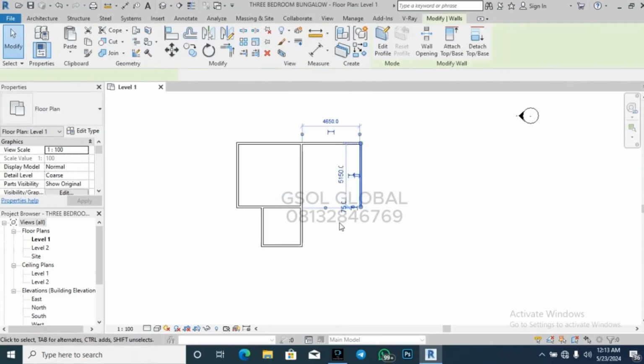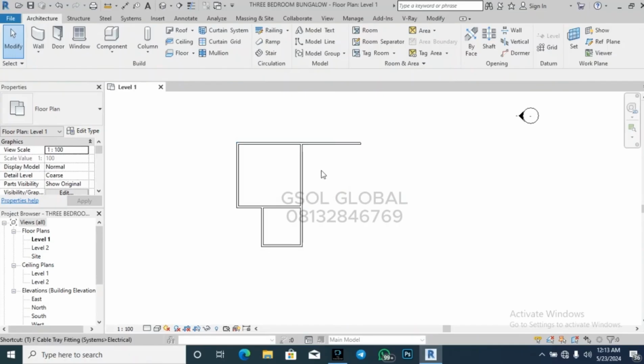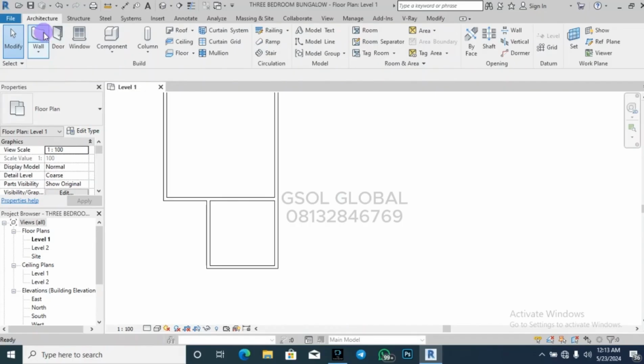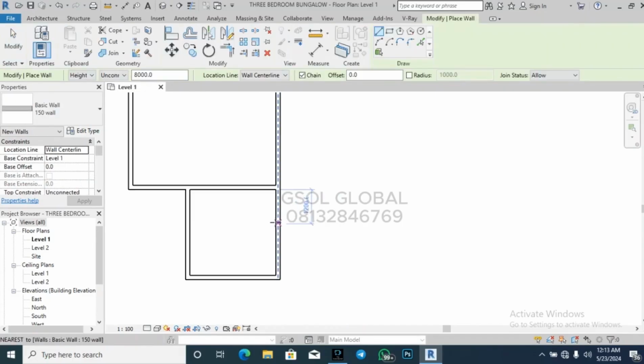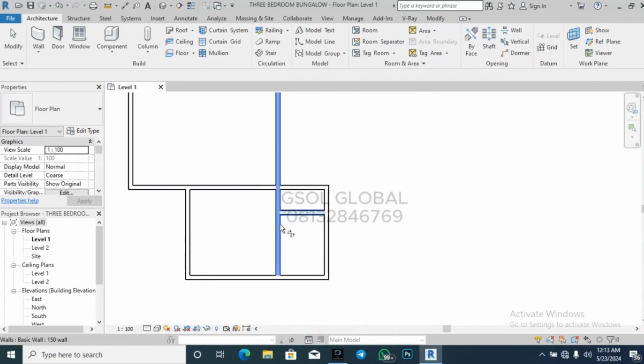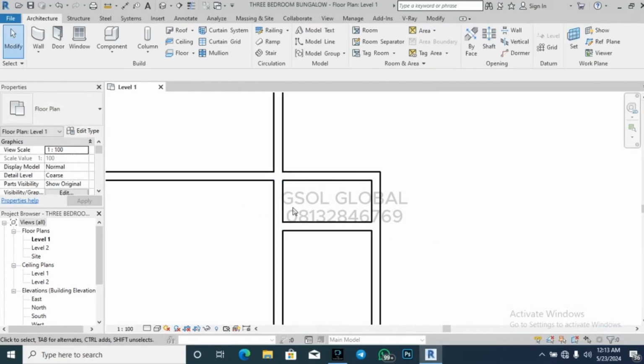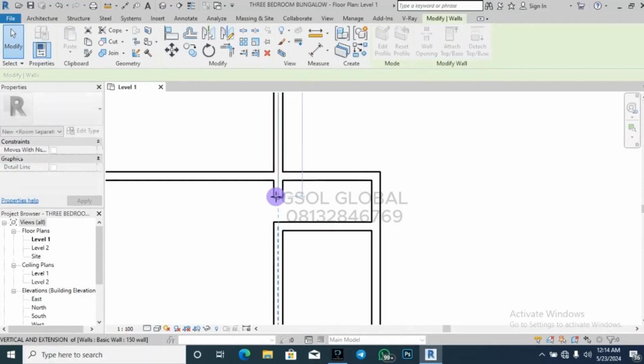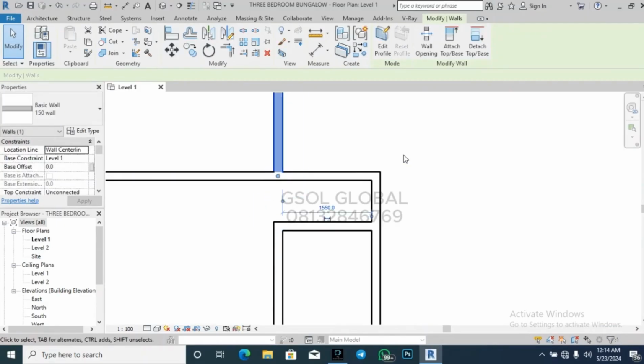Okay, so let's go. I've already seen what I want to see. All right, so now trim and let's trim. I will just go ahead and put my visitors toilet in this place. All right, so I can put it here, and then I can trim, sorry, undo. We have to slit that place first. We slit this place to trim it properly. So I will trim, slit, then I will trim, and then click this wall, drag it into this wall.